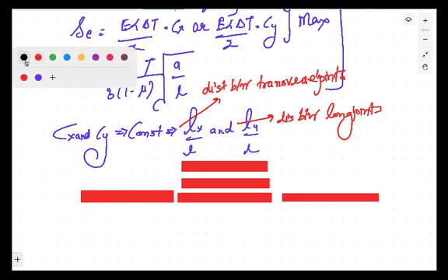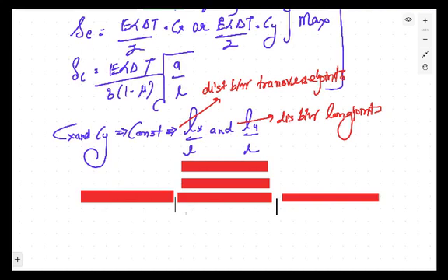Now, if you want to just see the joints, these are the transverse joints. These are transverse joints. And these joints are the longitudinal joints. It means that if you want to calculate the values of Lx and Ly, these values will be given to you actually. The Lx value, which is along the x-axis, is this, and this will be Ly. Now, this Ly is the distance between longitudinal joints, because these are longitudinal joints. Lx is the distance between the transverse joints, because these are transverse joints. Transverse joints are perpendicular joints, like this. Longitudinal joints are like this. These values will be given to you.